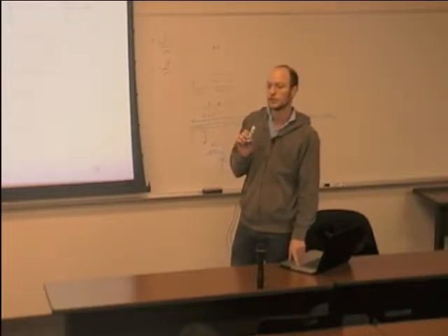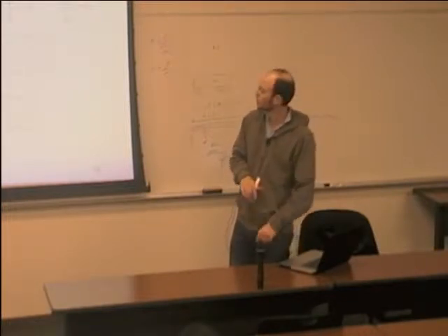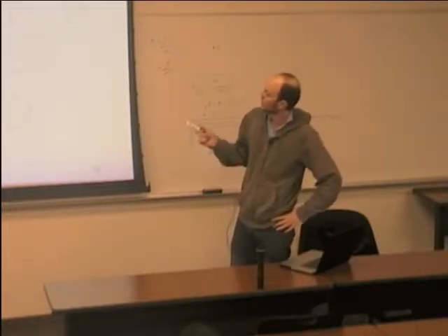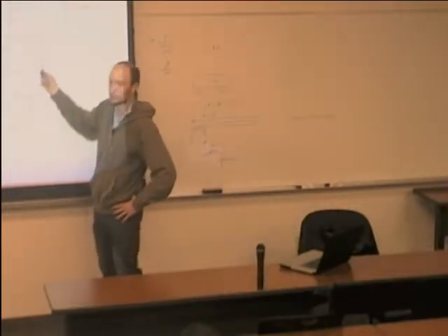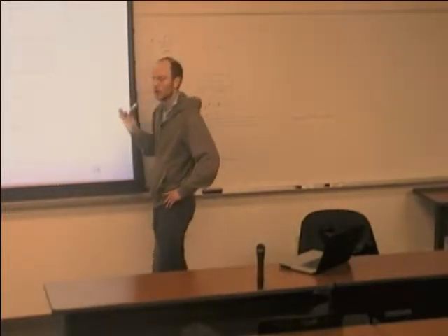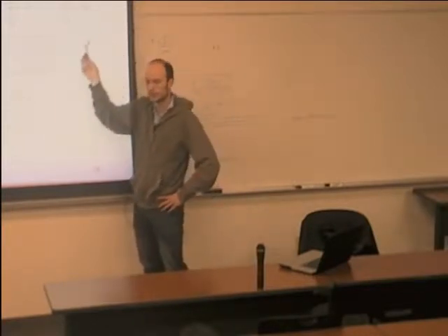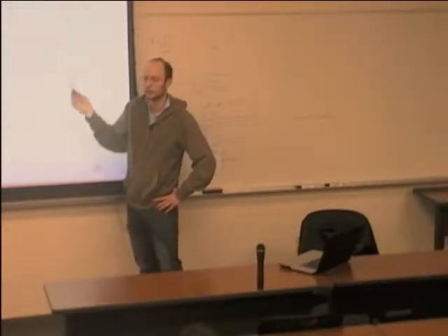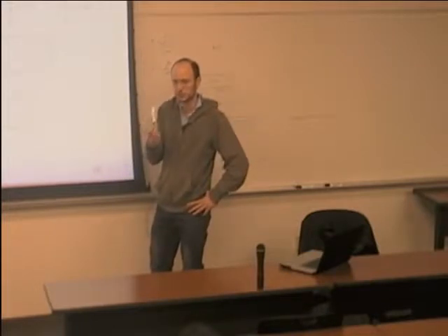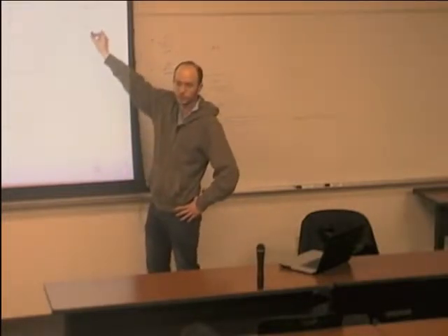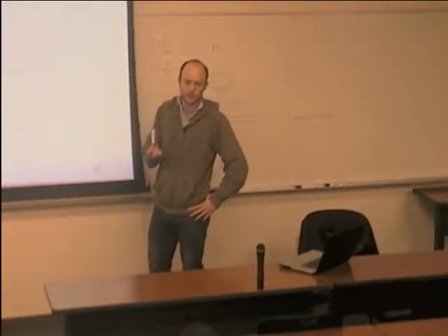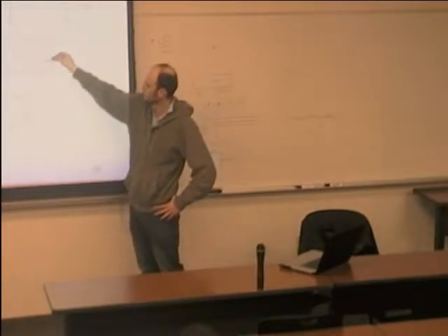For getting that tau, do you just do the integral of the Elmore delay? Yeah. So this is the equation. Because this is a distributed network, we are trying to approximate it with one time constant. We are taking essentially a system that has infinite poles, and approximating it with a system that has one pole.